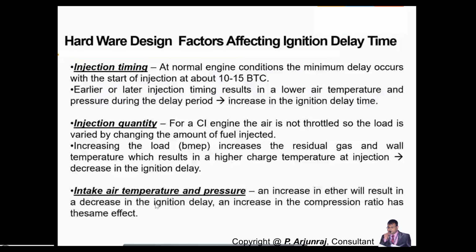And again, the inlet air has a temperature and pressure. An increase in either the intake pressure or the temperature will result in a decrease in ignition delay. You also have exhaust gas recirculation, EGR.